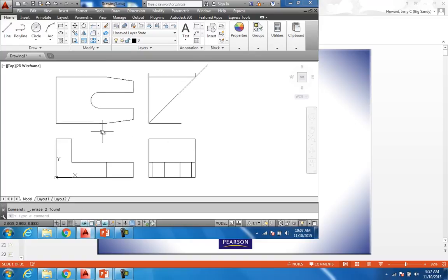Now let's go ahead and get the top of this thing. I want to transfer this width up here, just like that. And you can see on this thing, at the main top, we've got a 1 inch coming off the center of it. So we'll offset that line a 1/2 inch both sides. Boom, boom. Delete that out. So now I can take that and bring it straight over here, catch that point, bring it to right there, bring that one to right there, and because we know it's going to come down at an angle, we'll stop and wait on that.